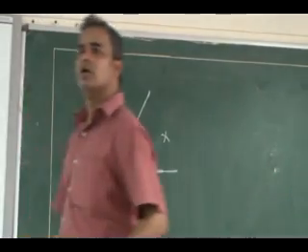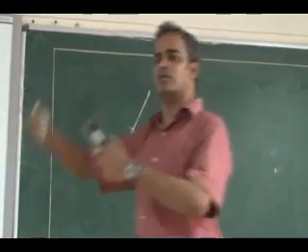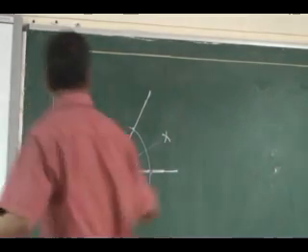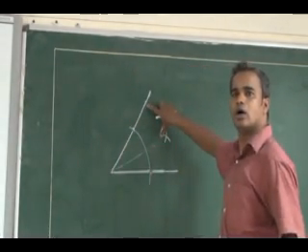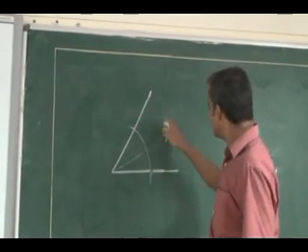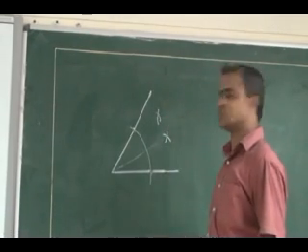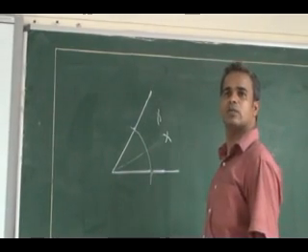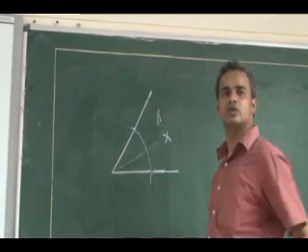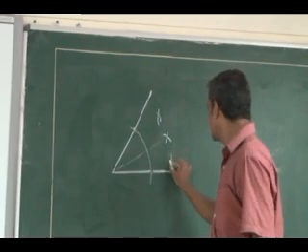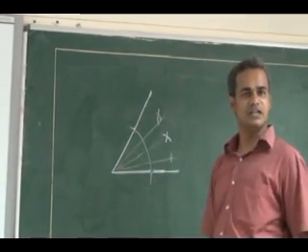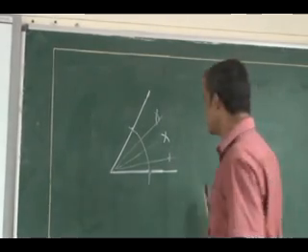Is it clear? Now similarly, for any equal number of divisions in a given angle, I can use the same procedure. Suppose I want to divide this again by 2, I can use these two, or occasionally I can have another intersection. I can divide this equally by 2. Similarly, this division I can make into another 2 equal halves. So I can use the same procedure for other divisions. For equal divisions, this is the procedure.